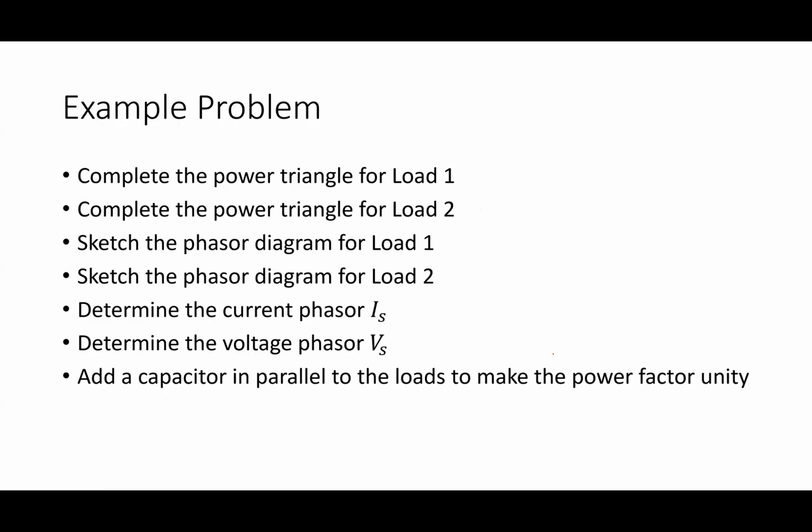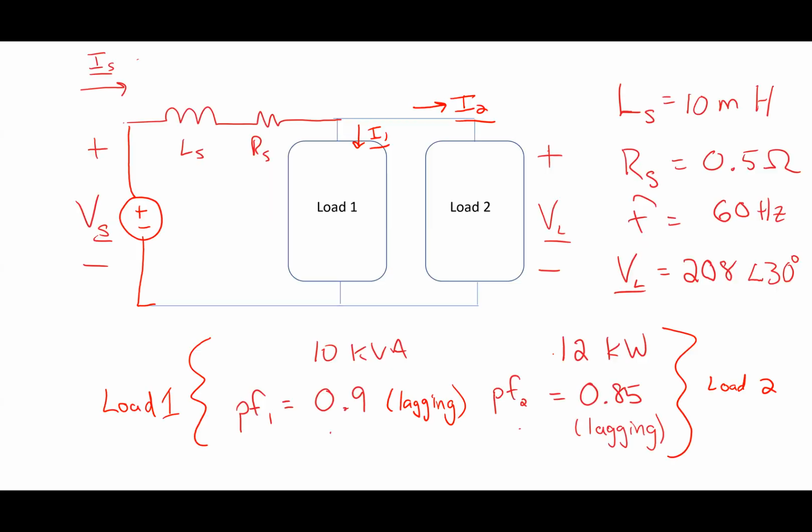Now, the last thing I say here is I want to add a capacitor in parallel to the loads to make the power factor unity. That's something that you may or may not have covered in 2112, but we're going to talk about that. These problems are pretty straightforward, but we have to unpack a little bit what information I gave you for load 1.